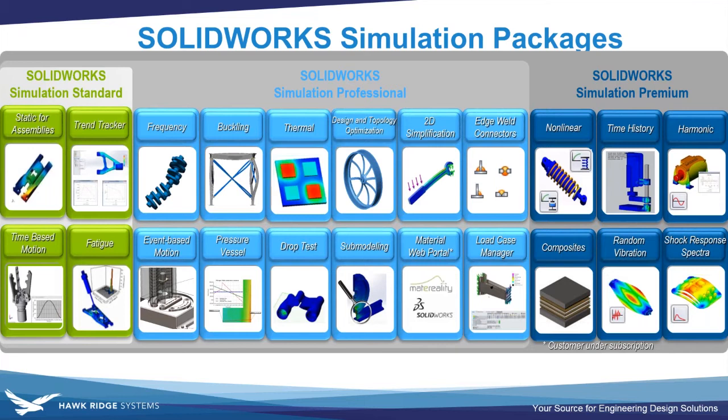You also get a fatigue analysis. The fatigue analysis leverages the information from the linear static to be able to see whether it's going to fail after a certain number of cycles. So you get a pretty good starting point here with Simulation Standard. Of course, that's not going to solve all your problems, or you may have different needs. That's where Simulation Professional and Premium come into play.